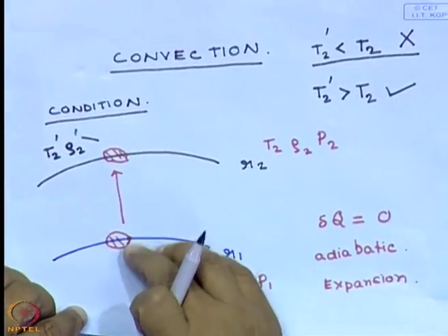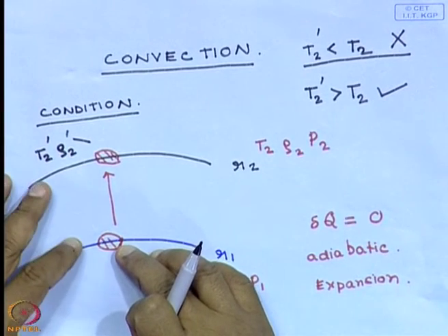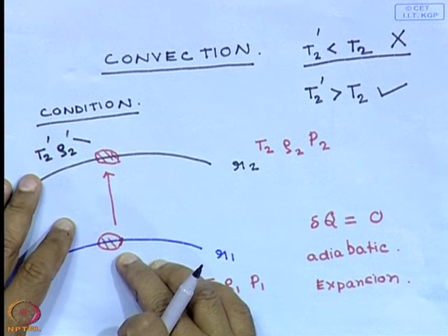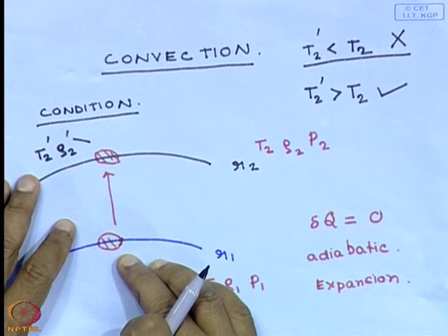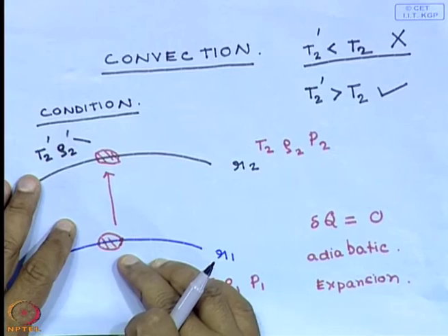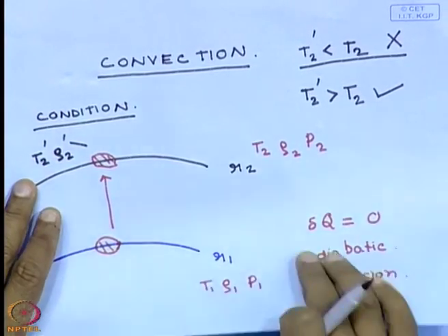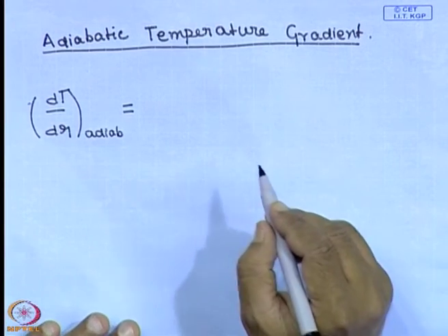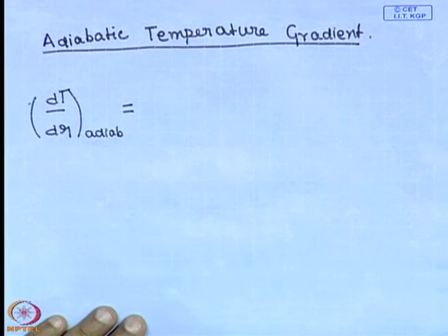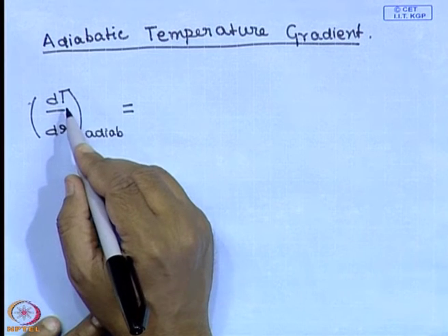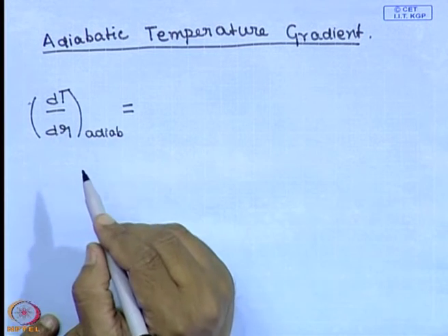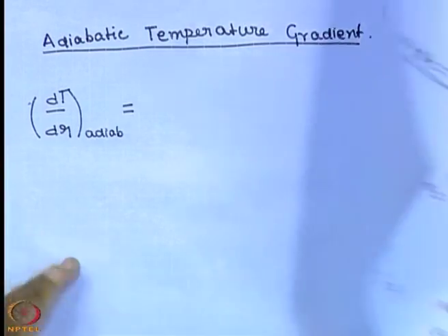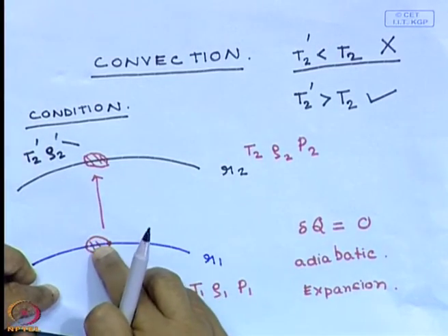The state of the gas can be described in terms of two state variables, that we know in thermodynamics. So, for this exercise it is convenient to think of the two state variables as the pressure and the entropy. So, the temperature of the gas is now a function of the pressure and the entropy of this volume of gas.